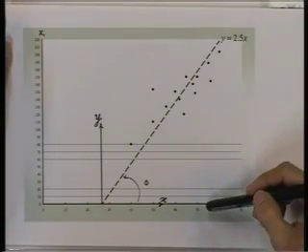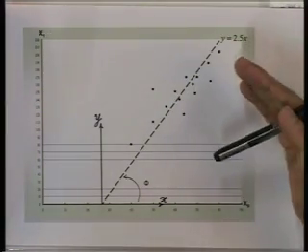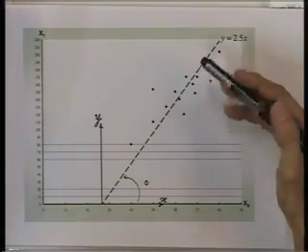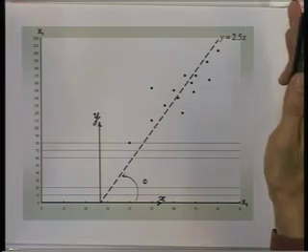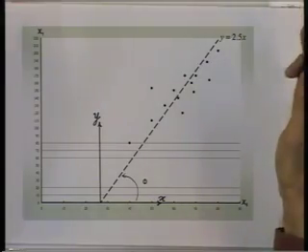And because the horizontal and vertical coordinates are correlated, if we quantize them separately, then the outputs of these quantizers will have a lot of common information, and this will not be an efficient way of transmitting or storing these pairs of samples. So, what should be done?